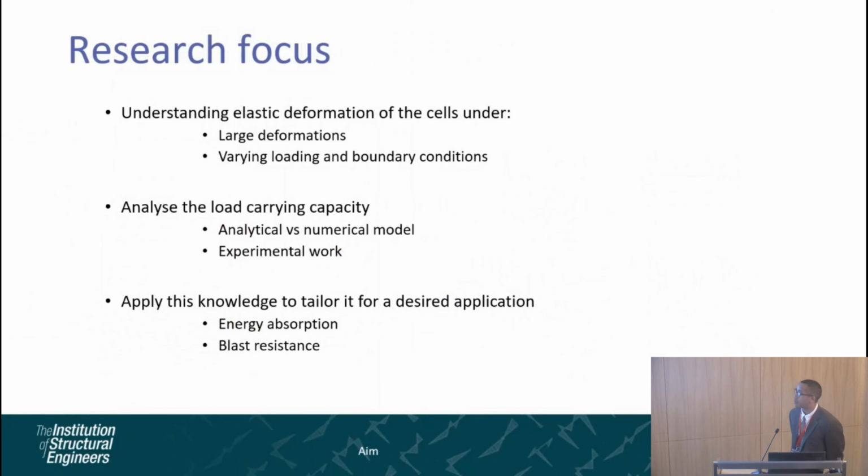So the research aim is to understand the elastic deformation of these types of cellular structures under large deformations, as well as with varying loading and boundary conditions. This will then help us to analyze the load carrying capacity, and the modeling has been done analytically for small scale models and numerically for both small and large scales, and some experimental work will follow as well. And upon having a clear understanding of how these type of cells behave, then we can tailor them for a desired application, such as energy absorption or blast resistance.